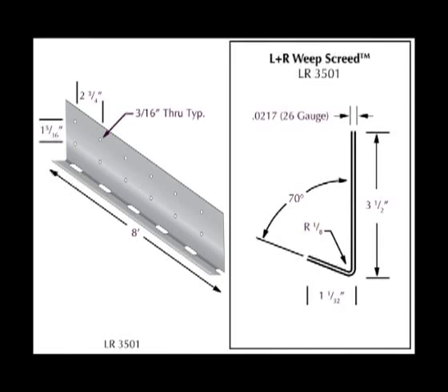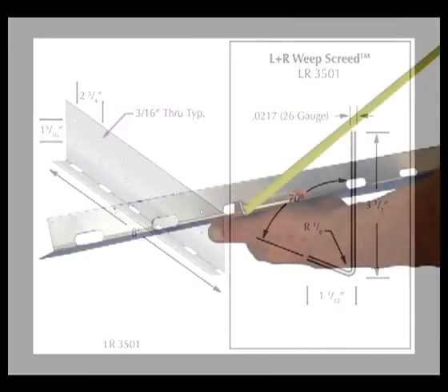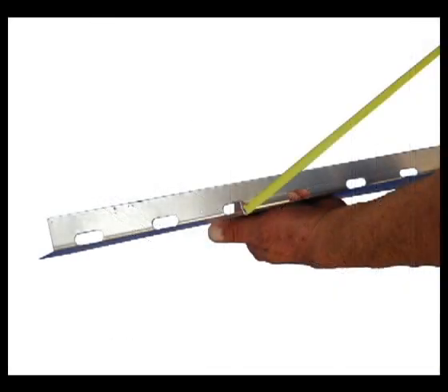This device creates a bottom of thin veneer wall termination that will accept the bottom edge of the first course of the WRB, rain screen drainage plane, metal lath, and the bottom of the scratch coat of stucco. While providing effective drainage capacity with large 1" slots placed frequently along the bottom edge, the 3.5" back flange is a flashing type of detail that covers up the construction joint created by the top of the foundation and the bottom of the rim joist plate.